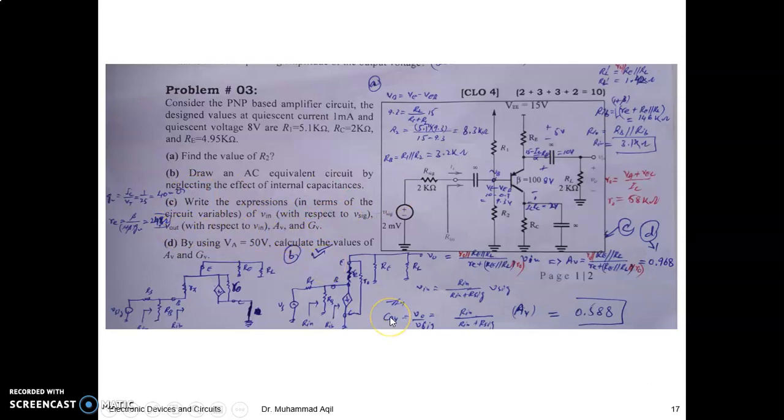V out, right? So as you had been doing in NPN transistor for common collector configuration, the same will be the case here. What about RIB? Because the input is at the base, you want to see the internal resistances of the transistor at the base. So R input at the base looks to be small re in series with the parallel combination of these three things, right? But times 1 plus beta, because these resistances are at the emitter, so you want to see from the base.